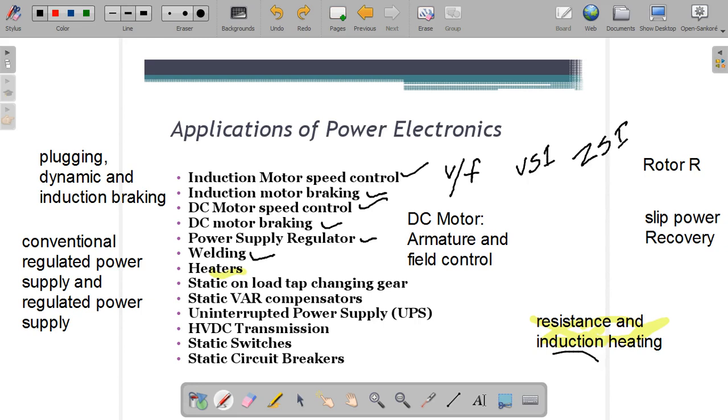This current induces an alternating magnetic field. The metallic job in this field cuts the alternating magnetic flux and an EMF is induced in it. This induced EMF causes the circulation of eddy current and thus heat is produced. If the supply frequency is increased with the help of semiconductor devices such as a cycloconverter, then the eddy current will increase and thus more heat is produced. Induction heating is also currently used for electronic heaters employing a rectifier, filter and inverter in sequence.